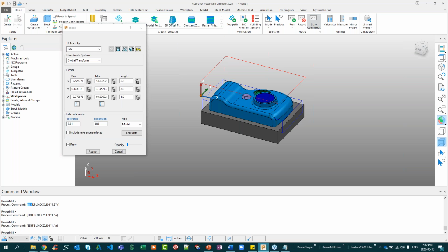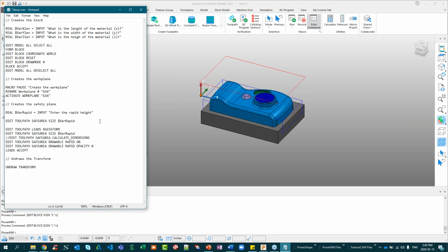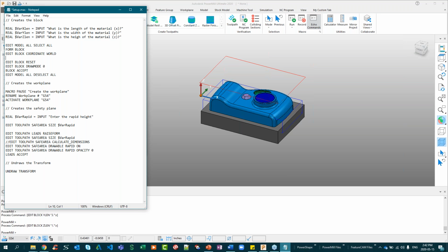So for the edit, remember, I don't need the hard brackets, just the actual parameter, and the backslash and the R is just a character term, which is not required. So it just depends on where I want to place it in here. I'm going to drop it in right after I establish the coordinate system, because I'm going to lock the coordinate system to the global transform. And at this point in time, I'm going to put this value in,